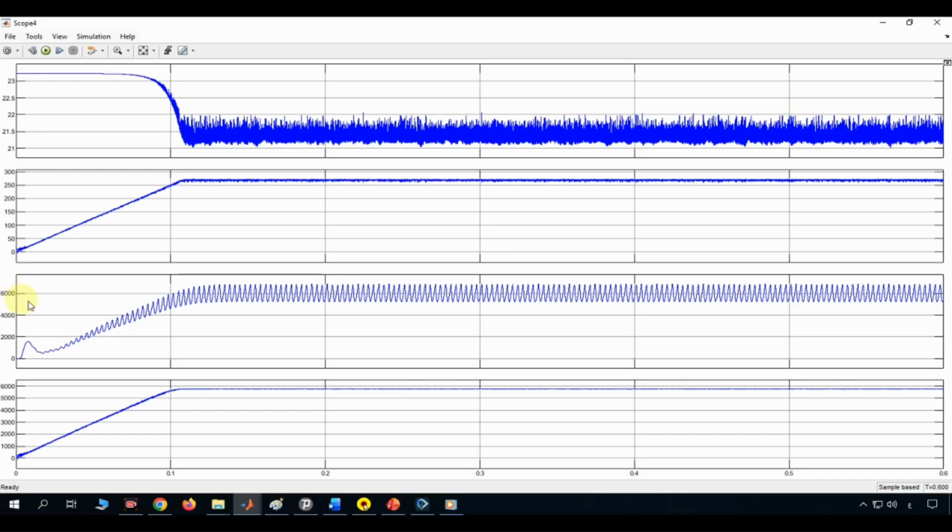This shape makes a lot of sense if you think about what happens when you multiply the first 2 signals together. Power is voltage times current, and both of those signals were doing their own settling and oscillating during that same startup window. Multiplying a ramping voltage by a current that's also changing produces exactly this kind of growing oscillation during startup, followed by a steady ripple once both underlying signals have reached their own steady states. So this trace is very likely the instantaneous output power of the array, complete with the switching ripple inherited from the voltage and current it's built from.